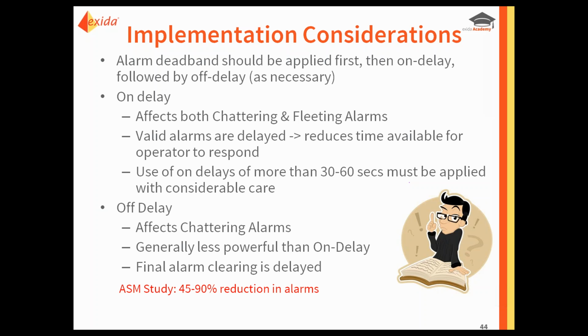And as I mentioned earlier at the start of this, the ASM Consortium study found that application of deadbands and on-off delays, based on, for example, the guidelines in this technical report, when they did the study and measured the results, they found that it reduced the actual alarm load on the operators by 45 to 90%. So not small potatoes.